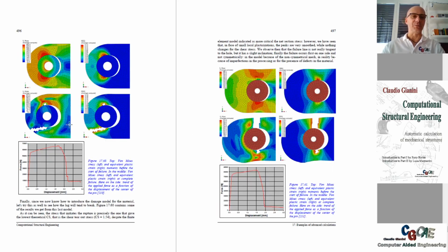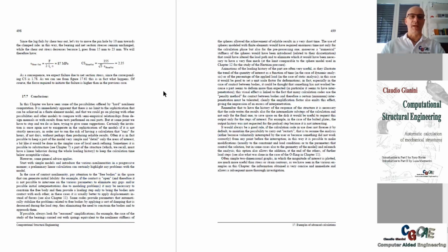And then again, by simulating the damage of the material, we can simulate the shear tear out failure mode. And if we then increase the section by moving the hole a little bit more inside, in order to make the net section the most critical failure mode, that is what we see here. As I already said, the descriptions of the figures invite you to visit this link and to see the animation of what is happening. And basically that's it.